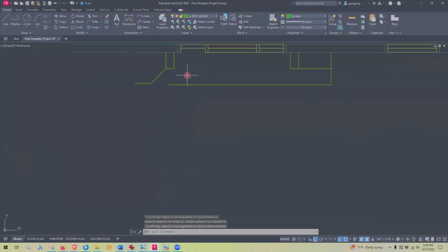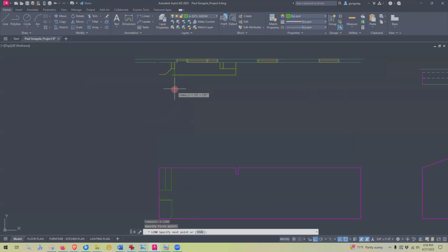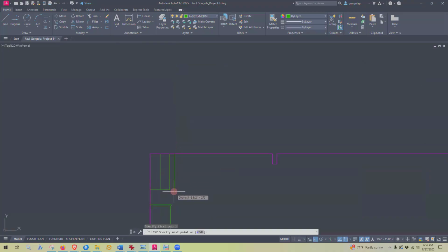And let's get this silly little shelf here. Again, I'll do the same thing. You know what, this time, just to keep it fresh, I'll O-track down. So I'm just going to hover over that corner, looking for that green line, and I'm coming down right to the ceiling right there, left click, and now I'm drawing. Then I will hover over that corner, find that object snap corner there, intersection, and then just go around like that. And that is my cabinets.